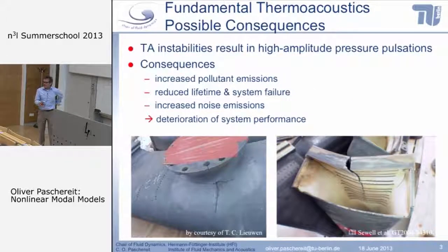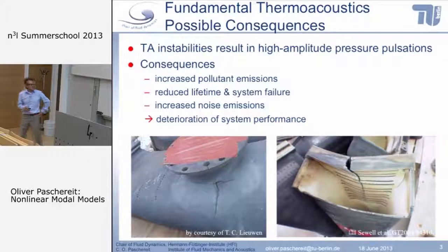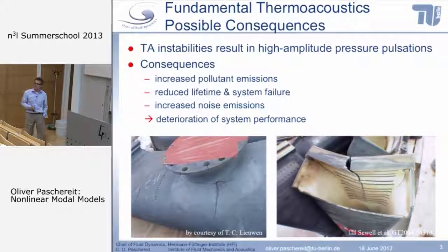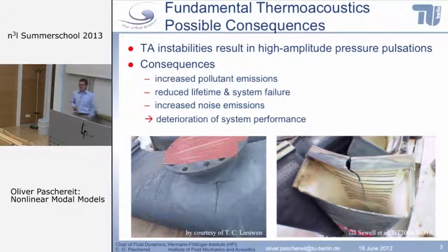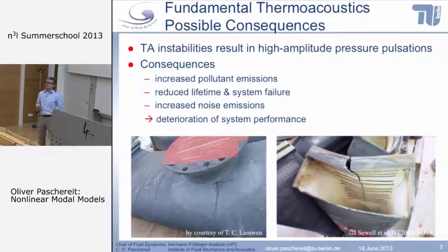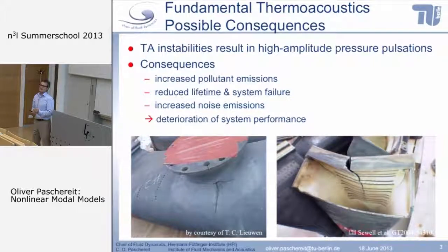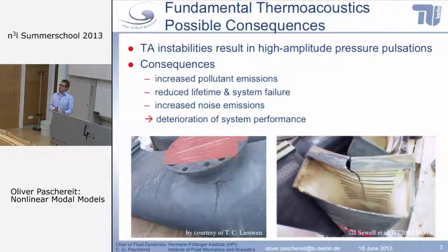And that can lead actually to damages in the combustor. Although I'm always hearing when I show this slide, actually this figure here is taken from Tim Lieuwen, if you talk to people in industry, they say, well, combustor damages we don't have anymore. And I'm sure about this, that probably you can work around it, but what definitely is still an issue, and that leads me maybe to part of my answer whether thermoacoustics will still bother us in the future, is that of course it somewhat limits your operating cycle.